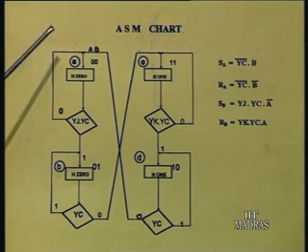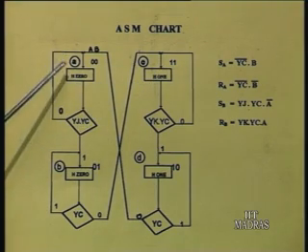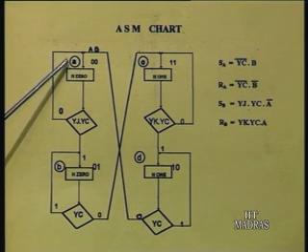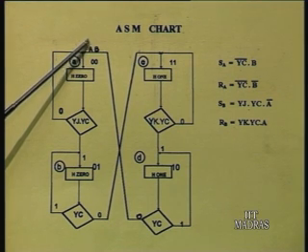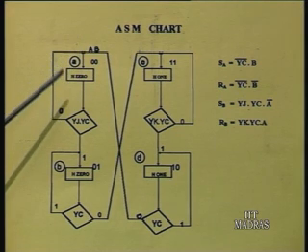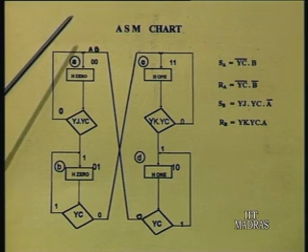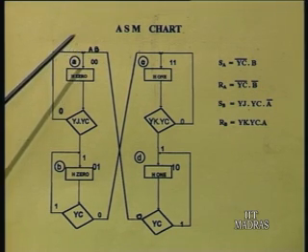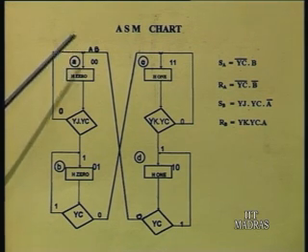Now, this system, you may call it a machine, is in one of 4 states at any instant, a, b, c, d, which can be represented using 2 state variables. What are they? Capital A and capital B. These 2 state variables will physically be represented using 2 latches, and we considered 2 SR latches. Strictly speaking, it is an S bar R bar latch, which we discussed earlier; we may call it loosely an SR latch also.